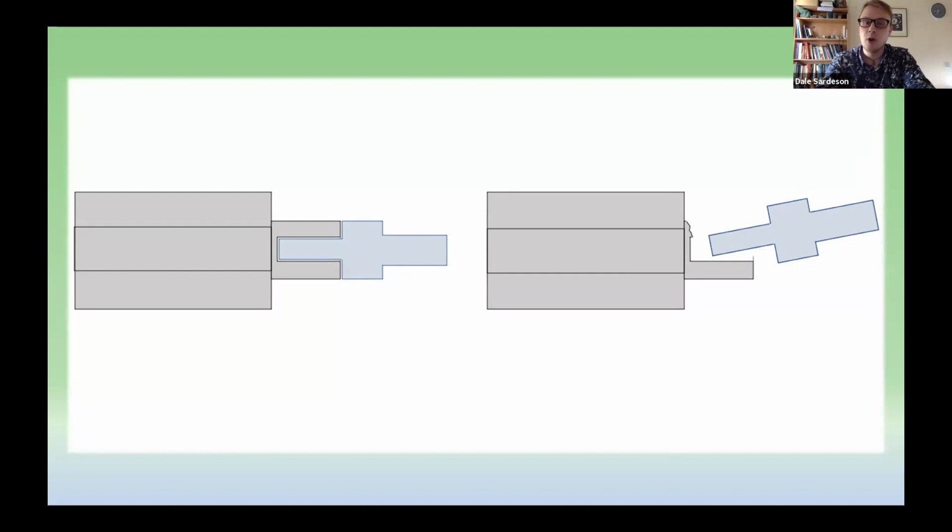Whilst there was no longer any visible stress fracturing in the point that I had drilled into the arbor, it was obviously still weakened. And this being the locking wheel, it undergoes a significant abrupt locking force after every striking cycle. The arbor had basically failed so that my extension was able to fall out. And so the very thing that I was trying to prevent with the repair had happened. The pivot failed, the wheel fell out of meshing, and the train unlocked. Fortunately, there wasn't any other damage caused besides some slightly bent lifting pins, which were fairly easy to straighten up.